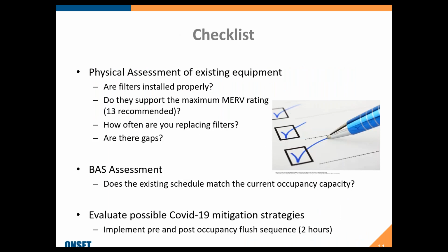So, I think one of the biggest things is the physical assessment, and it could be just simply opening these things up and checking, is the filter in there properly? If your system supports the maximum MERV rating of 13, I believe they do go up to 16 actually, but they're recommending that. What's your rate of replacing filters? Are there gaps? Just looking at it, any place where air is maybe not going through that filter, you could use something as simple as duct tape just to close up those holes.